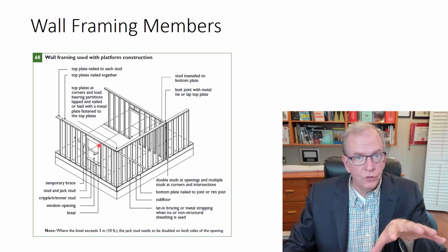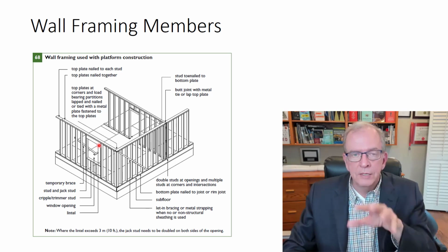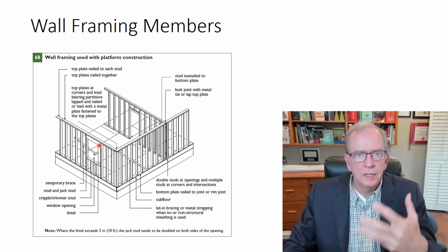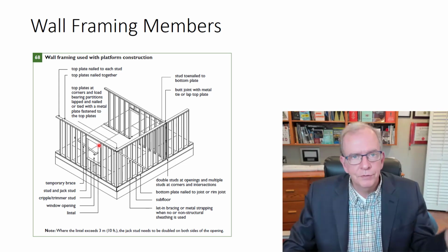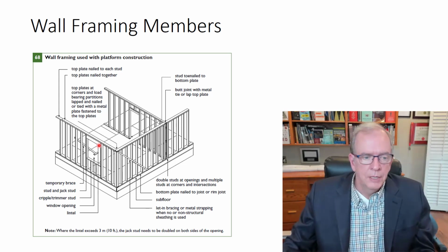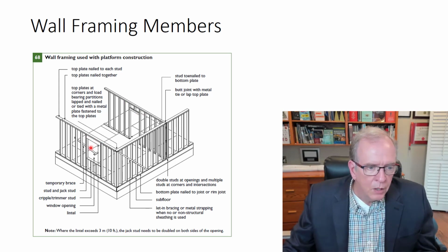And the construction drawings themselves will call it a lintel typically. All right, so like the ones I've been using, Cassidy and Company, very good drawings, they'll call it lintel. That's because that's what it refers to in the building code, and that's what it's designed to. So all of those beams going over your windows and door openings, horizontal in the walls, are lintels.